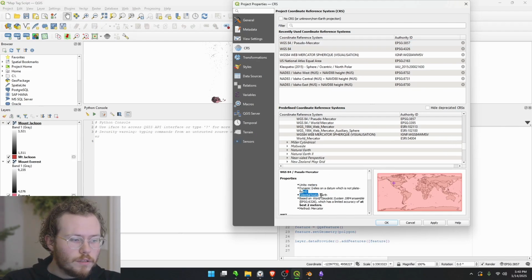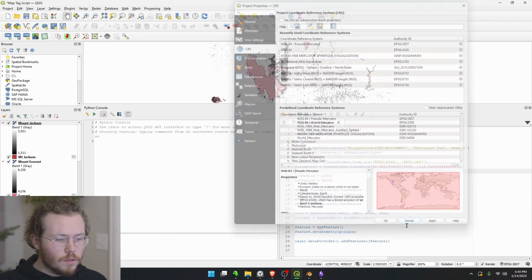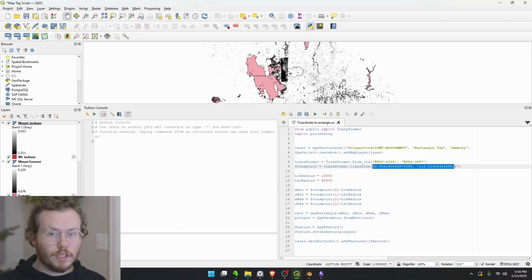Units are in meters, and it's a pretty standard map that you'd see anywhere. So I'm just going to leave that as is. This transformation not only changes what units we're inputting our position in from latitude, longitude to the meters that this map projection uses, but it also will transform all of the elevations to meters as well.